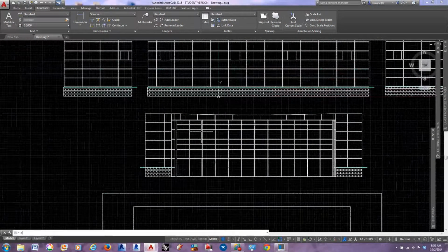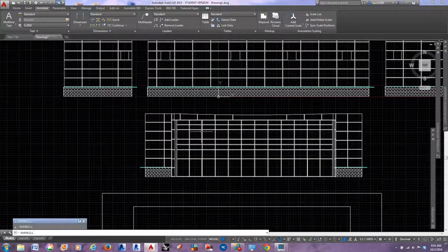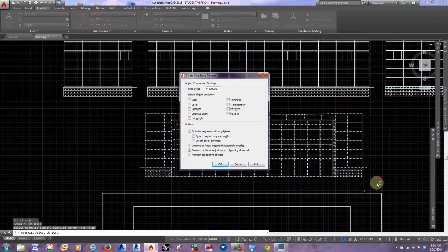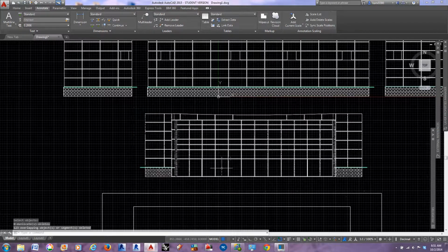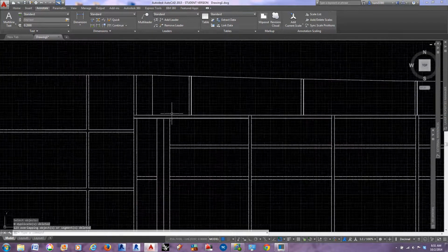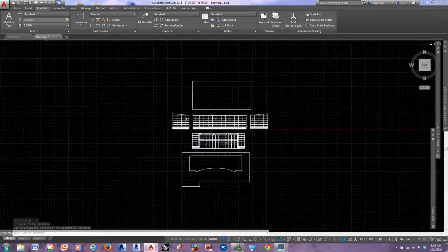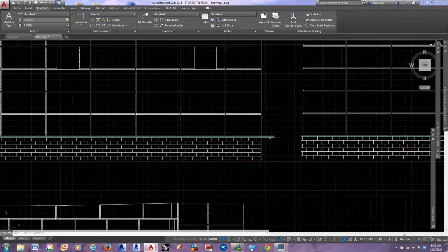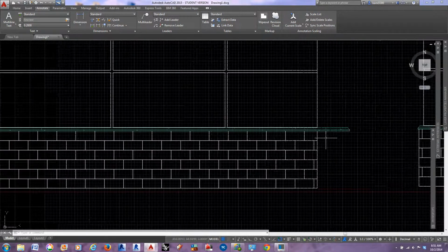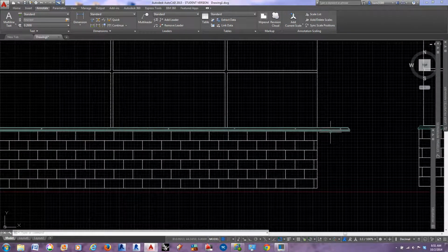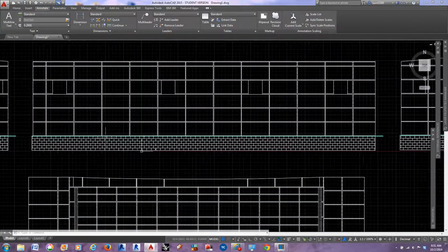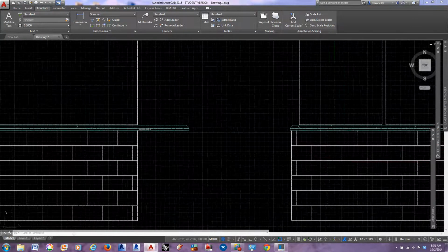And let's just type in overkill one more time and double check that there aren't any extra lines back there. Okay? Oh, as I scroll in, you can see those are also blocks. We'd want to go ahead and unblock those as well.